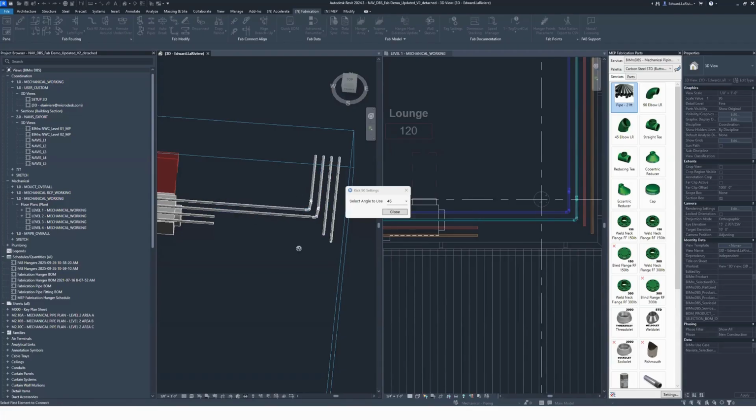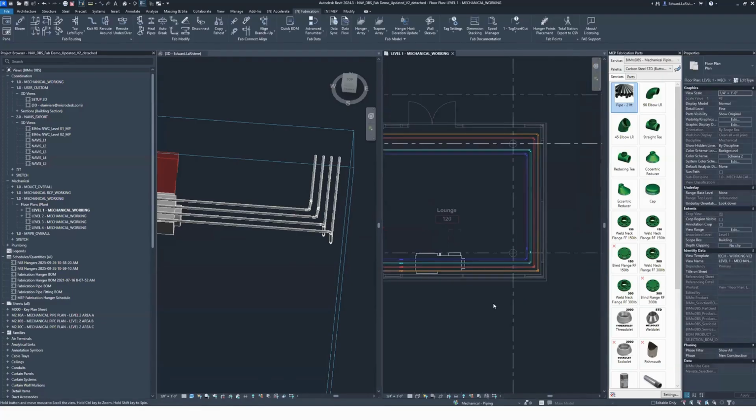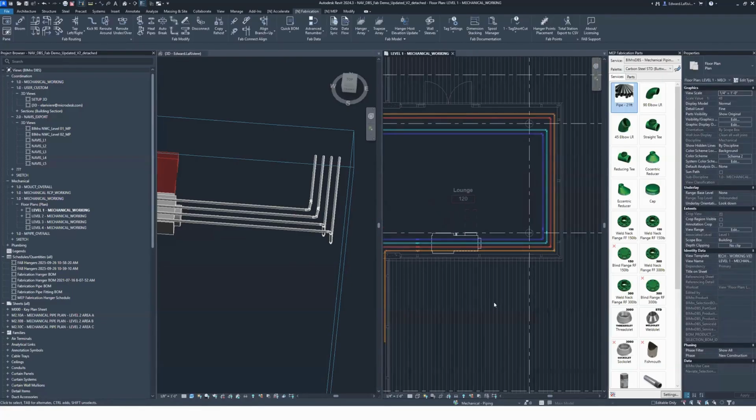We're just extending these to match, which also means if you want a trim tool that works in a 3D view, you can leverage this with a 90-degree angle to do the exact same thing trim to corner is doing, but inside a 3D view and without placing all those extra couplings. Let's coordinate those couplings at the end of the project. Let's make sure we can go in once this thing is done and start optimizing those. We don't need to do that as we go. That's how you wind up with too many couplings.